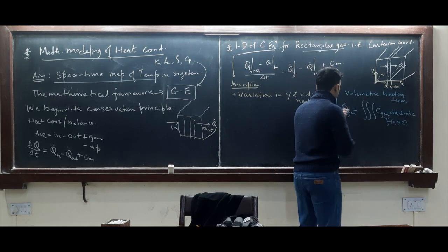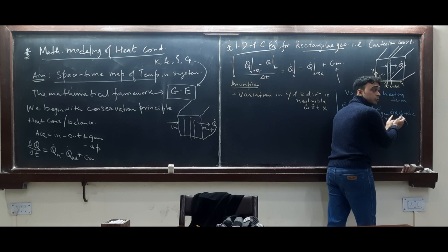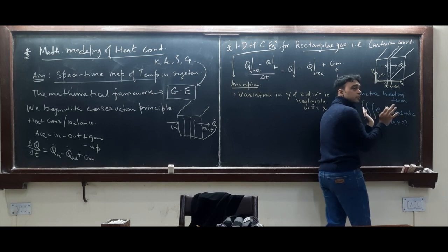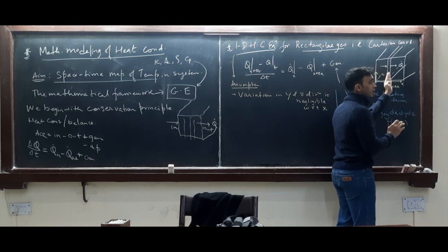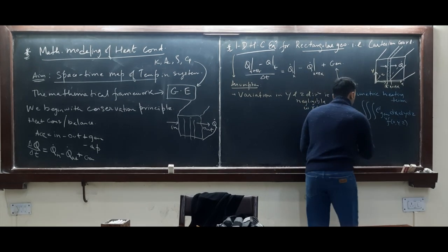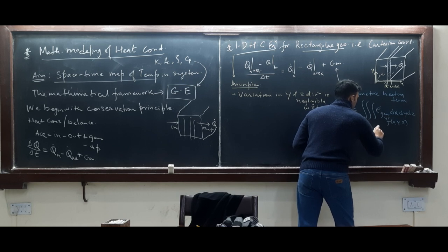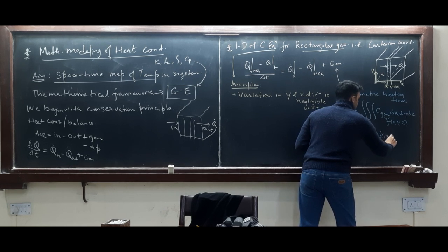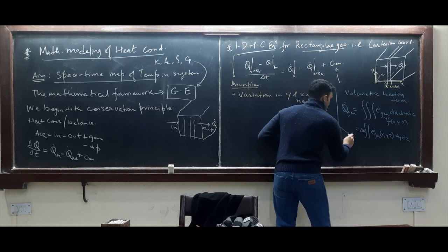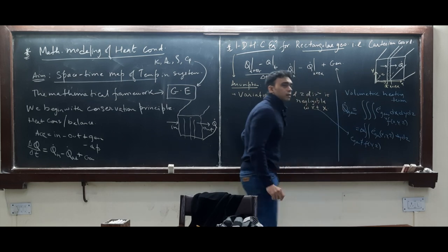So, under this assumption, can I simplify this further? Since my dx is a small element anyway, it will not vary much, because it is already infinitesimally small. So even before putting in the assumption, I can take the delta x out, E gen, which could be a function of x, y, z as of now, dy, dz. Now I'll use this assumption and say E gen is not a function of y and z.